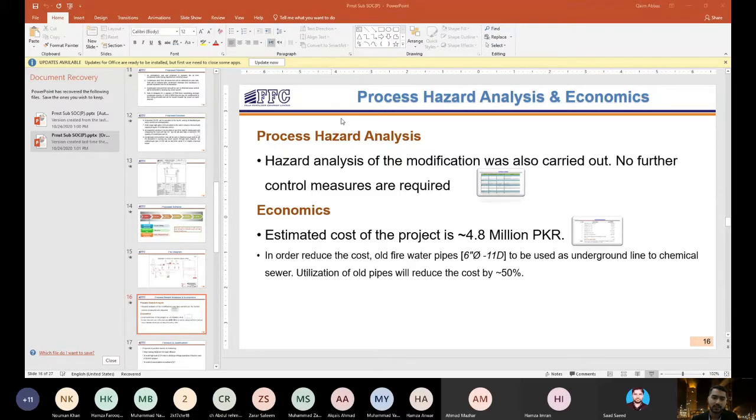So consequences would be that the tank may overflow or overpressurize. The safeguard is the overflow line provided for the oil or condensate overflow, which is directly connected to the existing system. So in case of overflow, the oil or the condensate would go to the sewers. A sight glass is available on the tank as well, and the breather is provided to avoid overpressurization. Similarly, low tank level could also be caused by human error, with natural gas breakthrough in the CY channel, that is the chemical sewer.